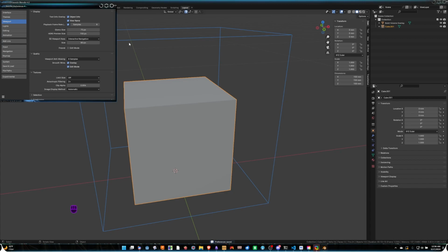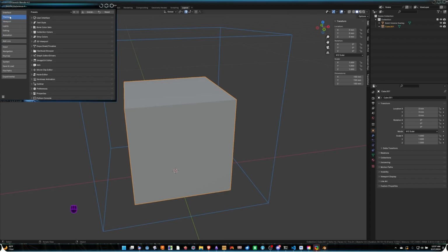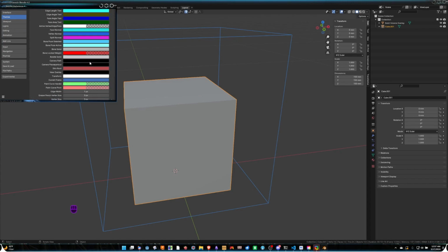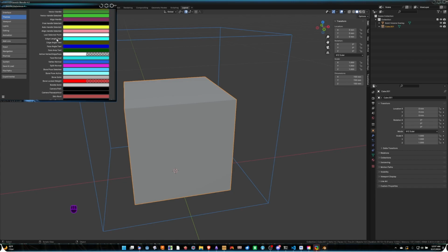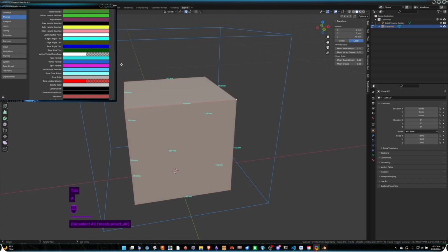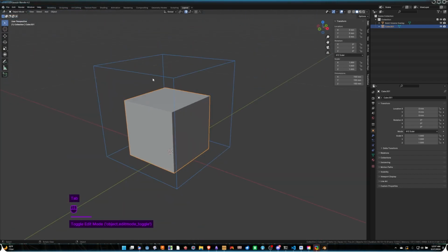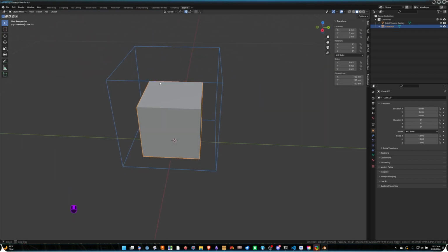And you can always edit your edge length text if you come to themes, 3D viewports, and you can scroll down until you see it say edge length text, and then you can set the edge length. And we can preview that right now. I can select all of my faces, edge length text, I can set the color of it, and you can see what that looks like. That's pretty cool. Okay, so go ahead and save that again. I know you can auto save, but sometimes it's better just to manually save it in case it crashes. Okay, so we're all set up and good to go.